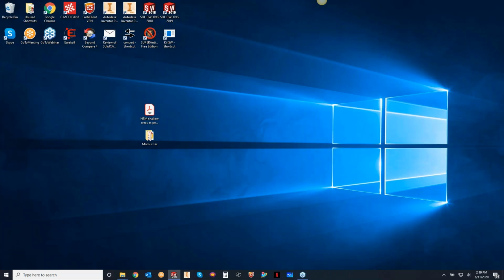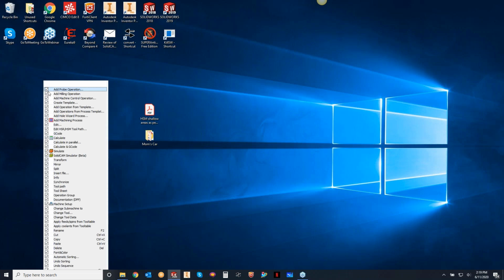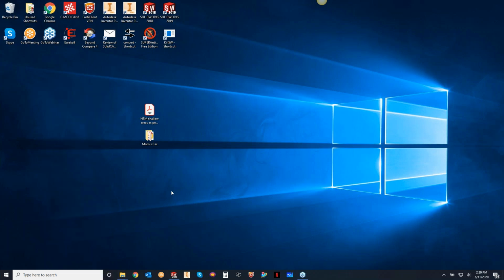And if I right click on my other window and go to customize, you see this guy pop up here, and this allows me to uncheck the box next to whatever I don't want to appear in that right click menu. So if you wanted to declutter your window with stuff that you don't actually own or buy, you didn't have license for, you can uncheck those boxes and then it won't appear in your list. So that should help you to declutter your menus.